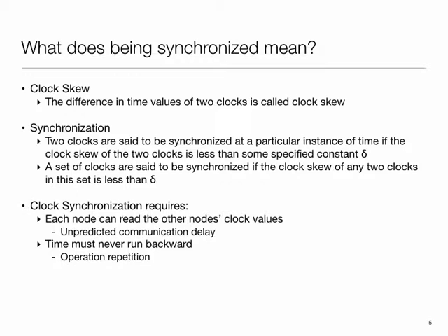And finally, there is phase being synchronized. And what I mean by that is, let's say I ask the two systems to generate a square wave of a known frequency. One setting could be they both generate the square wave. The square waves individually have identical frequencies, but they're phase shifted. For them to be phase synchronized, the phases will also need to be the same. So there are these three separate types of synchronization needs that may occur.